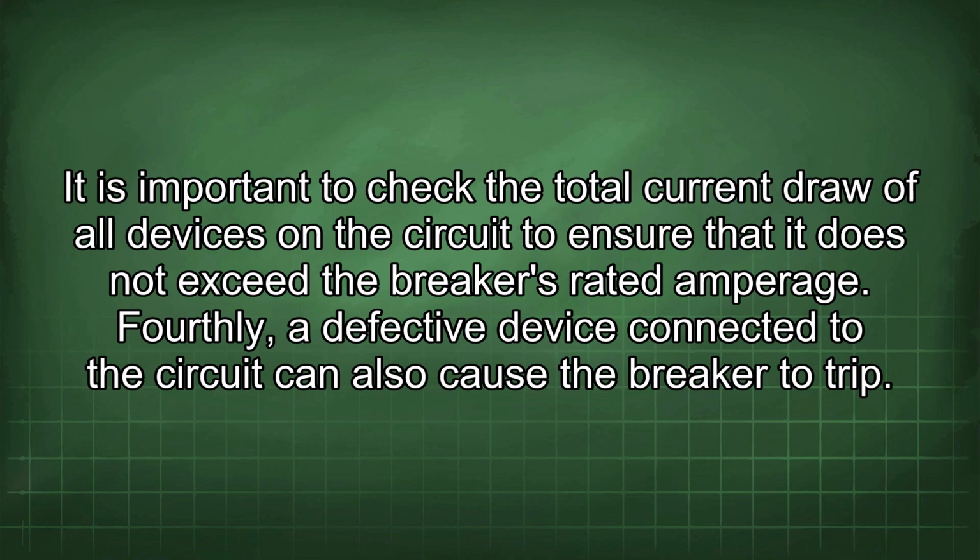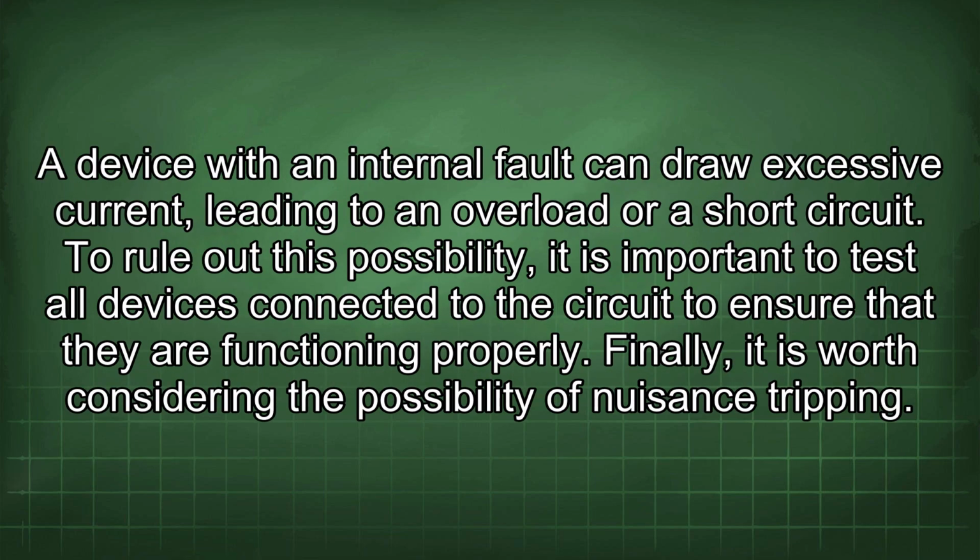Fourthly, a defective device connected to the circuit can also cause the breaker to trip. A device with an internal fault can draw excessive current, leading to an overload or a short circuit. To rule out this possibility, it is important to test all devices connected to the circuit to ensure that they are functioning properly.